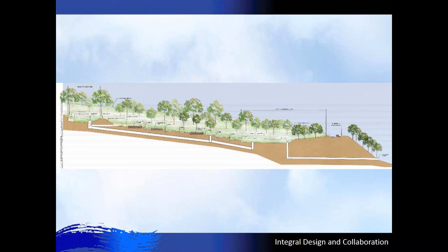That water flows into that pond, and then at a certain point flows into the pipe to the right that goes down to the creek. So even the massive large storm flows are going into a detention pond where we have an opportunity to do some water quality improvements with them before they exit to the creek.